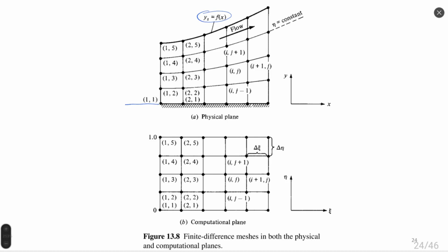Cells at the inlet, probably this is the throat where flow will start, will be smaller, not so high, right? And since the number of cells is equal on entrance and the exit, these cells would be bigger. And because of this, all cells would be different. There are no equal cells in this calculation.